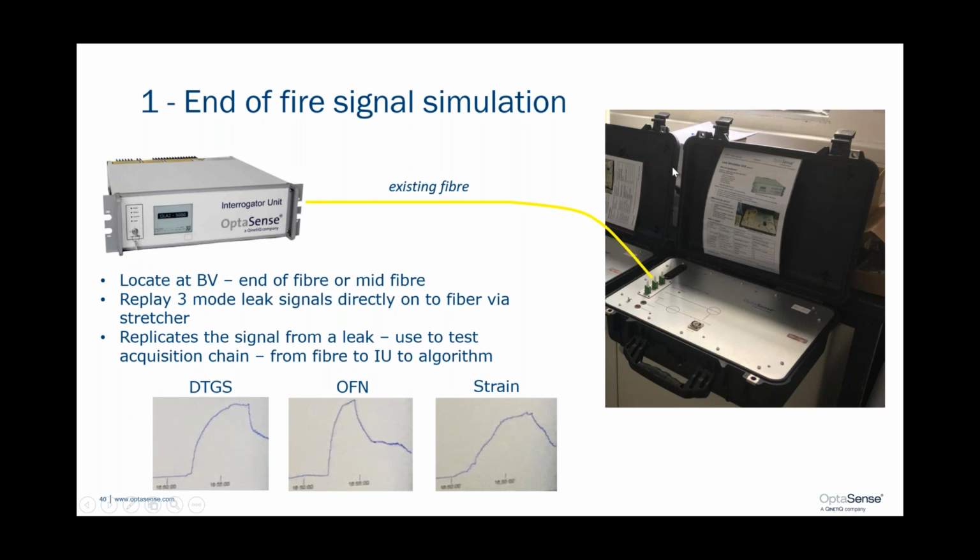So it's a single unit, it's a single location. You could splice it in at a block valve location, you could put it in different places, but it's a fake leak you're creating. But nonetheless, it's easy to achieve, it's quite low cost, and that allows you to validate any of your units. You may have more than one on a system, to verify that it is working as intended. Connect the system up, run the test, demonstrate that the leaks appear as you would intend on the GUI.